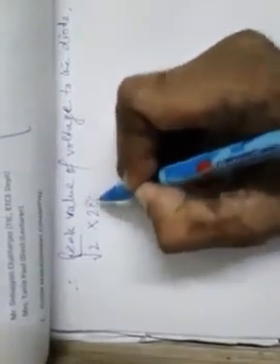So therefore the peak value of voltage to any of the diodes will be how much? You have to multiply the RMS value, that is 280, which we have found, by root 2, that means 395 volt.